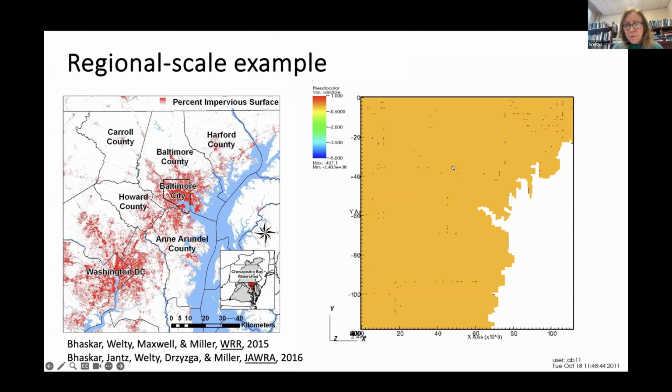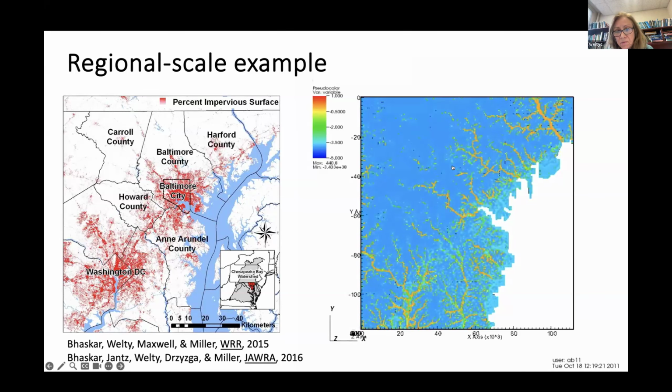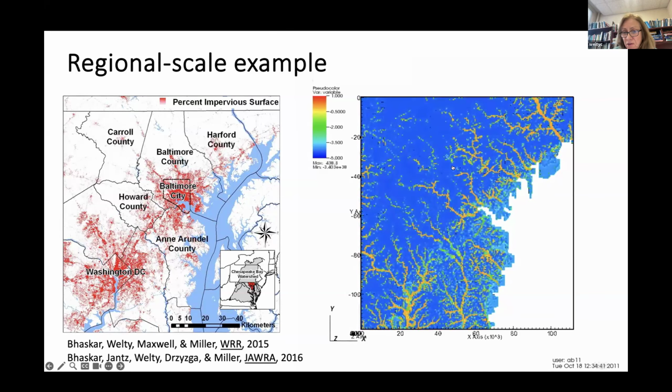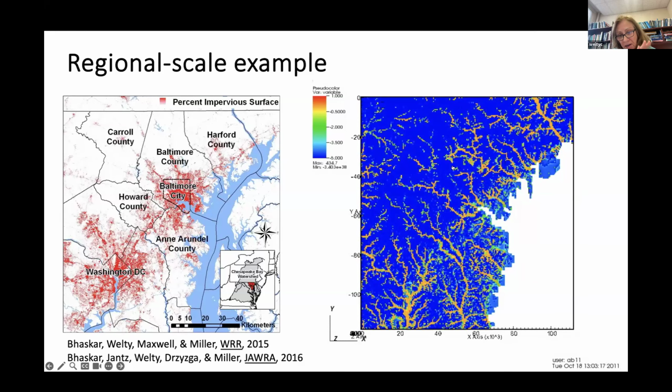When we populate this model with our data and then generate the stream flow, what I'm showing here on the right is you can see the streams develop. We initially drape the water table as an initial condition, some depth below the land surface, and then as the model is spun up, the water table rises in the valleys and drops in the hills, and water fills up the streams. You get stream flow, and we always want to ensure that the domain is draining, that water doesn't back up. So we do various tests in the beginning. This was actually a drainage test slide, not a spin up slide.